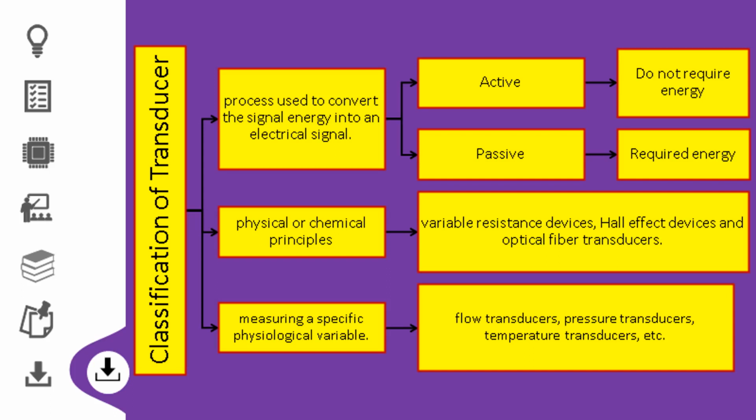Oops, I forgot to mention the term loading effect. Actually, this is nothing but the large consumption of energy by the transducer, which is called the loading effect. If the energy consumed by the transducer is large, then it may affect the measurement. Therefore, it will affect the accuracy of the medical instrumentation.